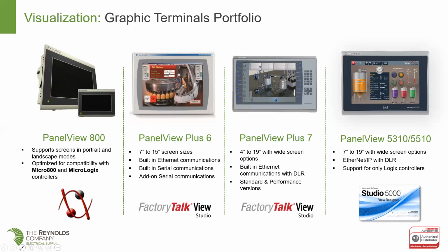The PanelView Plus 6, like we said a moment ago, is at end of life, and we'll have a picture of that here in a moment too. But PanelView Plus 6 has been around for quite some time, and there's a huge install base of it. It ranged between a 7-inch up to 15-inch screen. It had built-in Ethernet communications and a serial port, as well as the ability to add on communication modules for some of the specialty networks or field buses, such as remote IO, ControlNet. Those are the 2 we seem to encounter the most: remote IO and ControlNet.